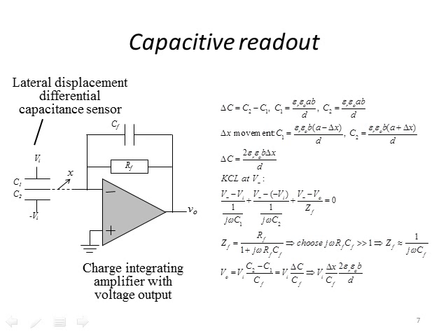And then V out is equal to Vi times delta X over CF times 2, the permittivity, times B divided by D. So the transfer function of this system is V out over delta X, which is equal to Vi over CF times 2 times the permittivity times B divided by D. So remember how to analyze this and the assumptions that were made with the feedback capacitor and resistor, or the impedance of the feedback network, in order to simplify the expression.